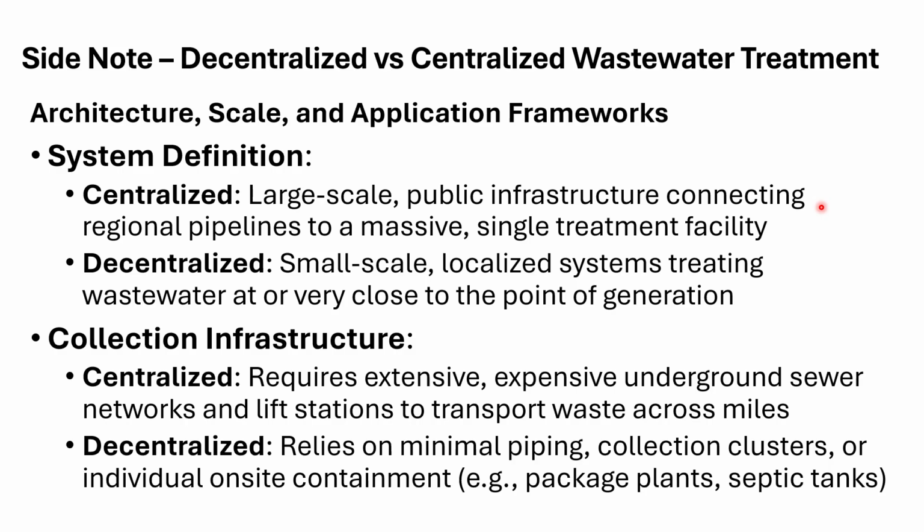Okay, that's centralized treatment. Okay, decentralized treatment, which is what a lot of people say, well, what on earth is that? Well, they'll understand what centralized treatment is. Even though they may not have heard the term, they'll say, okay, that's a wastewater collection system, goes to a central plant, gets treated, and then the treated effluent gets discharged, and the biosolids are managed. Well, a decentralized system, think small scale, think rural, think a bunch of septic tanks. It's all decentralized. Each structure has its own septic system.